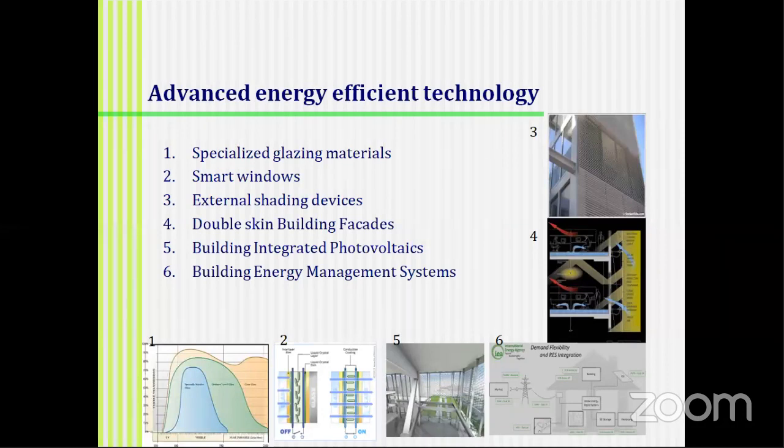Today, shading has become one of the major interventions that we are proposing in buildings. We had straight facades, glass facades, even 14-story, 20-story. But today we realize that we need devices to shade the walls, which can significantly bring down the heat entering our buildings. These shading devices could be in the form of louvers, or awnings, it could be a variety. But at the same time, it can become an architectural feature itself.